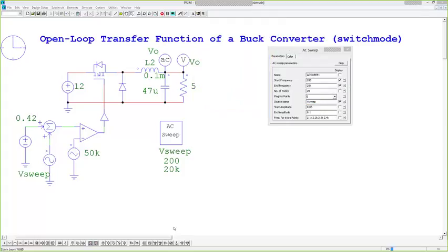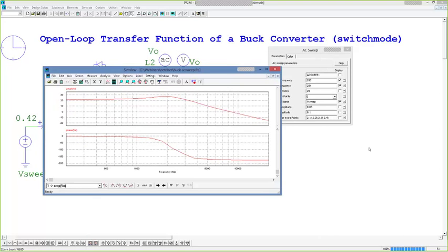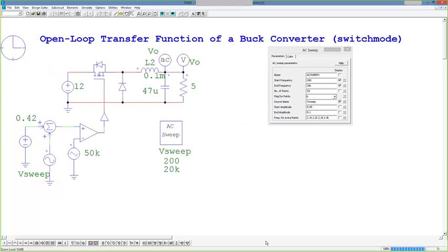So when you simulate, the parameter block here will take over this source and will run 25 simulations, the number of points there plus these extra points, and will run all those simulations, and then you end up with a frequency response. And then you can import this into Smart Control and go from there if you want to.